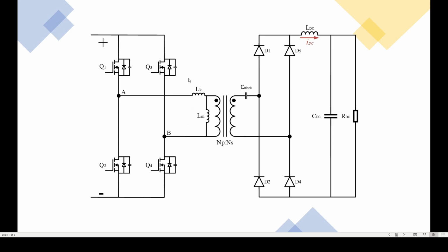In a usual full bridge, the duty ratio is changed depending on the load. But for the passive one, the duty ratio is constant at 50% for all of the switches, but the phase between the leading leg and the lagging leg changes over time.